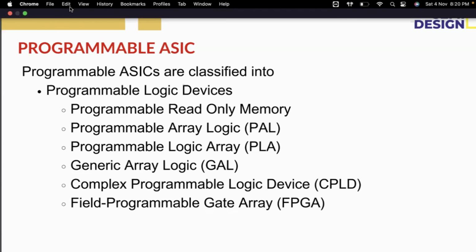And if you see the configuration of FPGA, how does it store the data? Using RAM, right? RAM is volatile in nature. So once power is off, the data will be lost, and the configuration is lost, right? That's why there is a disadvantage with the FPGA.